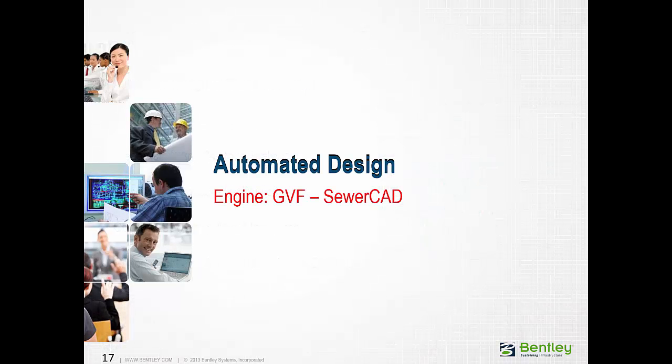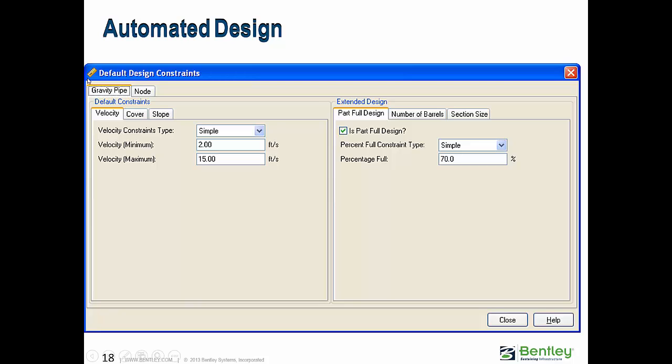Now let us take a look at the GVF convex engine in SewerCAD, and how it is used to automatically design the sanitary sewerage network. First of all, there is a tool called default design constraints. This is the place where the modeler can define the constraints: the velocity constraint, cover constraint, or slope constraint.